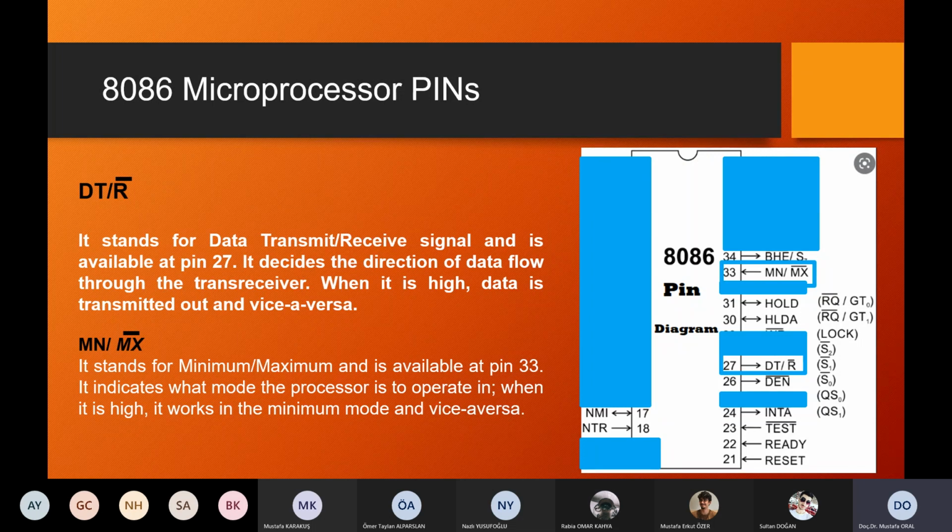So if there is more than one processor on the board, this input has to be connected to zero. This way, the 8086 operates completely differently from the minimum mode system, and all the resources have to be shared between the owners. The owners are the processors on the board.